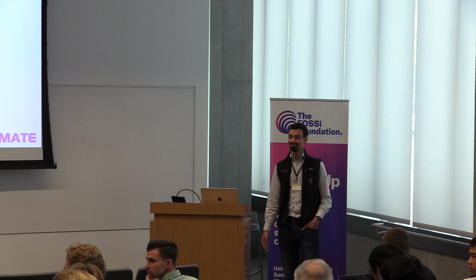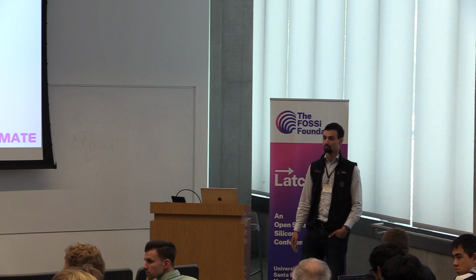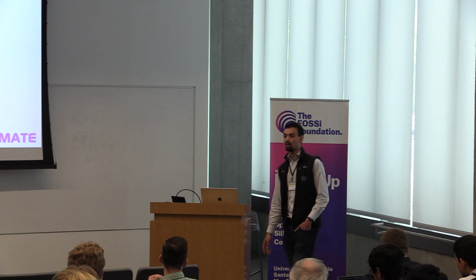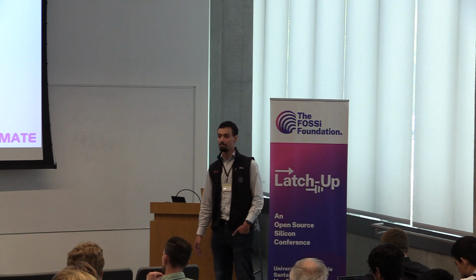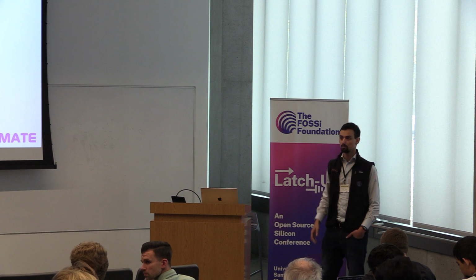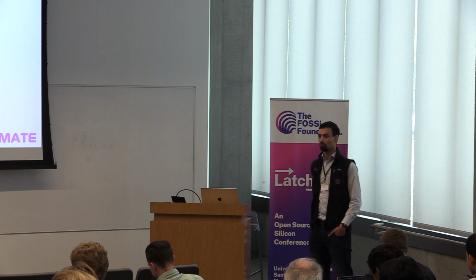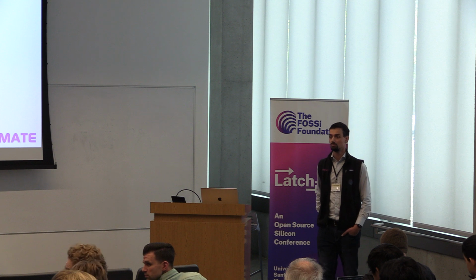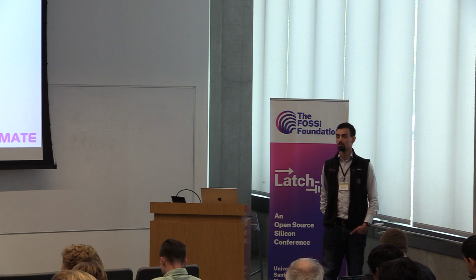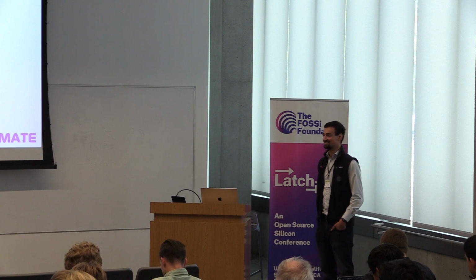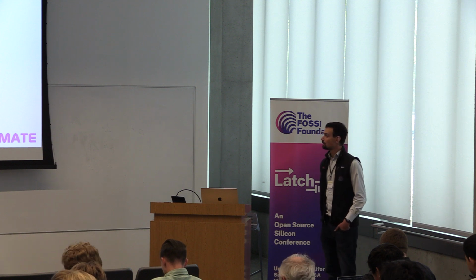Couple of things. First of all, you didn't mention support for derates. Yeah, it is supported. Derates are supported. And the second one is the difference between the STA that runs inside the PNR tools and the one run as sign-off. The main usage model is you want to take it out and create timing scripts, timing ECOs. Is that supported anywhere in this flow?